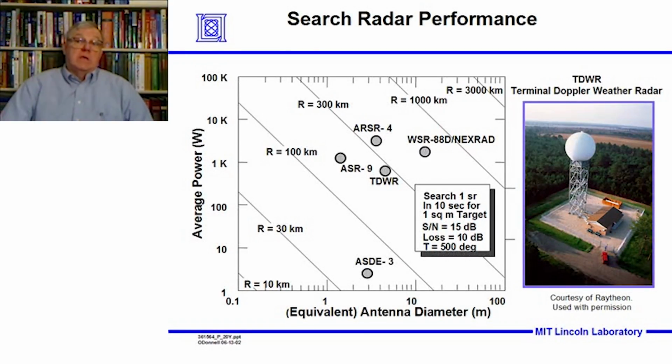But unfortunately, when they get on the other side of the microburst, there's a flip in sign, and a significant force pushes the aircraft further down. This reinforces the already downward push that they were trying to balance in the other direction, and pushes the aircraft literally right into the ground. Before these terminal Doppler weather radars were developed and employed, this phenomenon caused a number of significant crashes with a lot of loss of life.